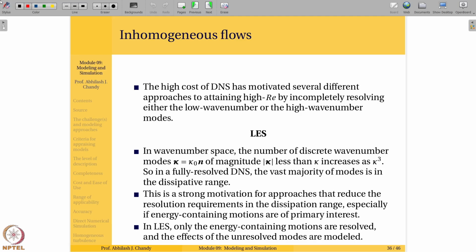One related to the numerical method, as I was saying in the last class, related to accuracy, related to the cost, the spectrum, things like the Kolmogorov length scale, Taylor scale Reynolds number, all that is very straightforward in homogeneous flows. That said, none of the practical flows have homogeneous turbulence. So it is imperative that we talk about inhomogeneous flows and have a discussion related to it.